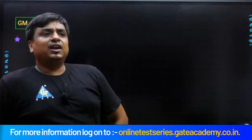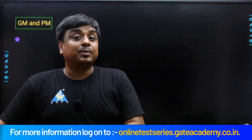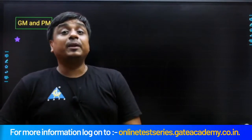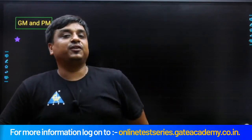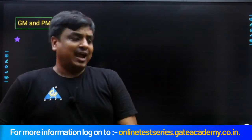What does it mean? Let's take n number of systems, out of which 4 are stable systems. You will not be able to figure out, of the 4 stable systems, which system is more stable and which is less stable. That means the relative stability was not known so far, but now gain margin and phase margin are the basis on which I can categorize which of the 4 stable systems is more stable, and in the end we are going to exploit the system which is more stable.